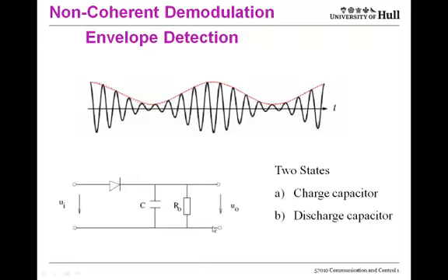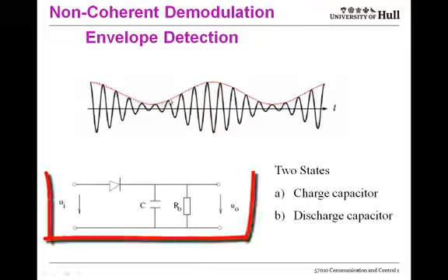So, the non-coherent detector. Those two methods, the superheterodyne method, relied on having oscillators locked to the oscillations at the transmitter. But the envelope detector doesn't need any local oscillator. It demodulates in much the same way you would with a felt tip pen, of just joining the peaks in the amplitude modulated signal it receives.